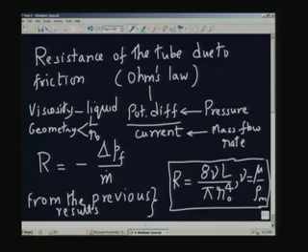And again, if the length is very long, if you have a very large column for the liquid in the manometer, you are going to have a large resistance, because L is occurring in the R here. The long length and small diameter are going to drive it towards overdamped condition, and of course, viscosity is also going to play a role, may not be very major, but the major role is going to be due to the length and the radius of the tube. Normally in practice, we take a manometer tube maybe a few millimeters diameter, 3 to 5 millimeters diameter, sometimes a little more. So, the diameter is going to be about 3-4 millimeters.